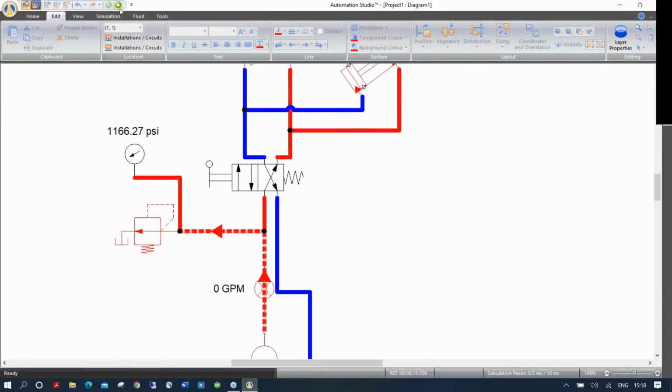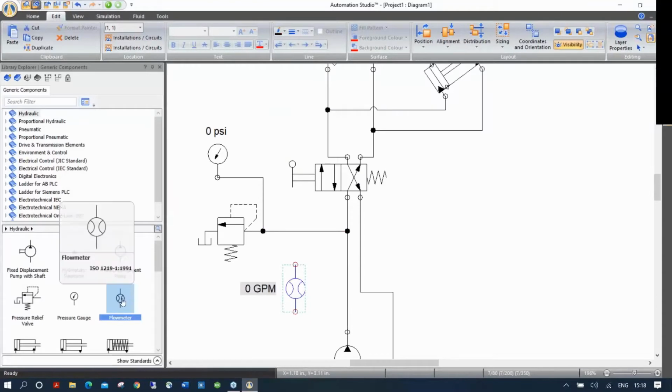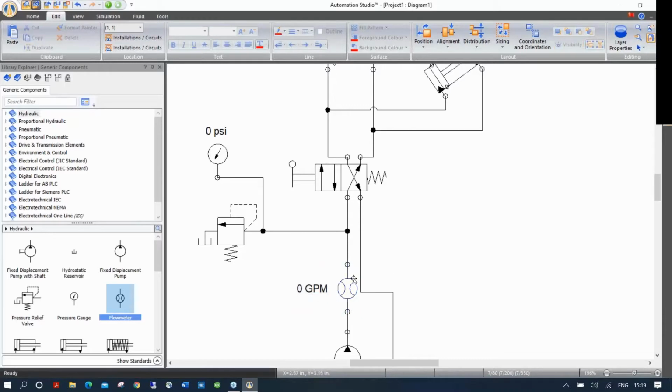So then you know something is wrong. So you can stop the simulation. Oh, my dots are red, it's not connected. So I can just take it off. I can delete it and take another one from the library and drop it directly. Or if you hold the shift key down while you move it, it will connect into the circuit.